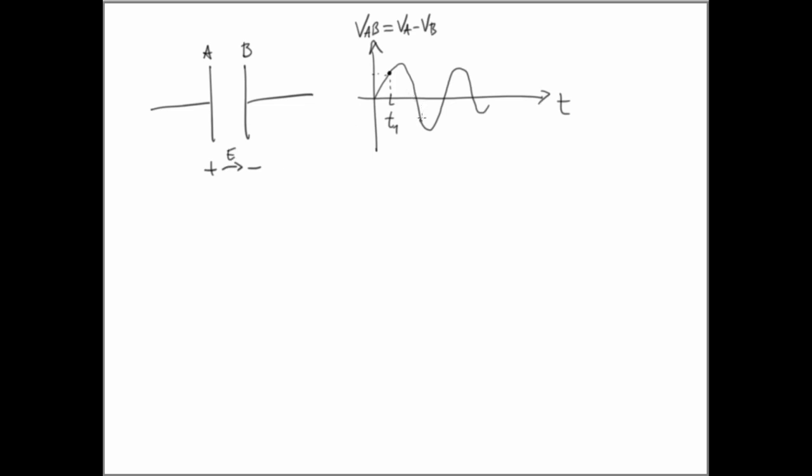While if we take another moment in time, which we call T2, the electric field would be directed in this way. So we can see that in the dynamic case, in presence of alternating currents applied to our capacitor, the electric field can switch direction. So it is actually the frequency of this signal that becomes very important now.